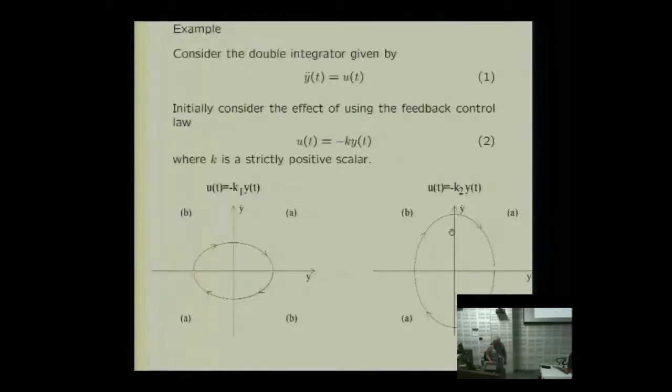If I look at what happens here from any point, if I start in the phase portrait to the left, I follow a sort of fat ellipse and I just go round and round the origin, getting nowhere nearer to the origin. And if I start in the second case, I follow this tall ellipse. So neither of those behaviors are desirable. They don't cause the point to go to the origin. And that would be a fundamental definition of stability. They're not disastrous either, because the system is not getting further away from the origin.